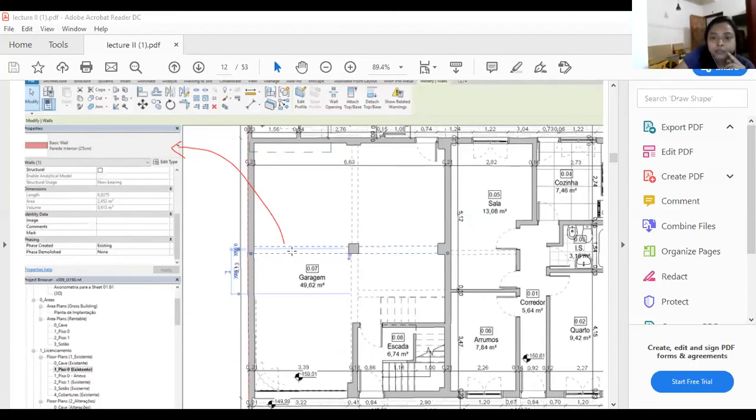Fine. Now this has been used to show the beam above this area. So there is this beam which is in this portion and this is the column. So the dotted line or the dashed line has been used to represent the beam in the plan. So suppose you have shown your section cutting from the sill level, cutting from the lintel height. So you are showing that you have something above the lintel height. So in that case, you can show this kind of dotted lines to represent your plan above.